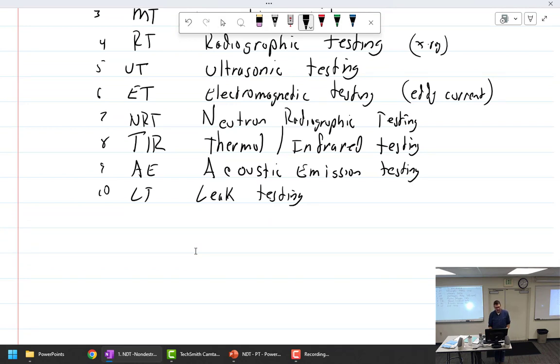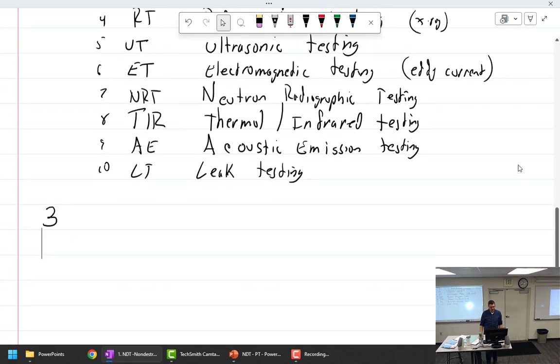Would you use some of these methods in combination with each other? Absolutely. Like Continental crankshafts, you have to do both magnetic particle and ultrasound. What if there's something you can do all 10 on? Specifically Continental, is that something they asked for? Yeah, something they asked for.